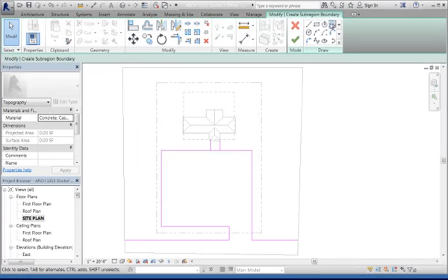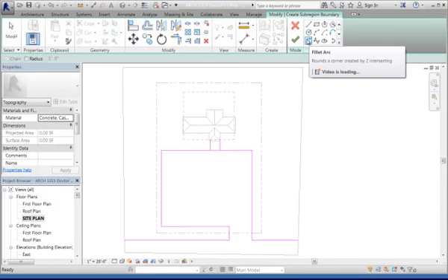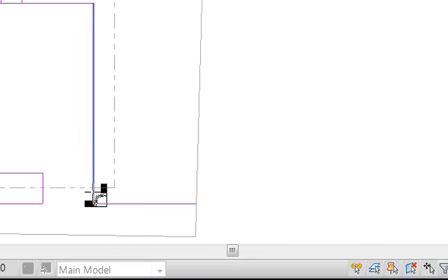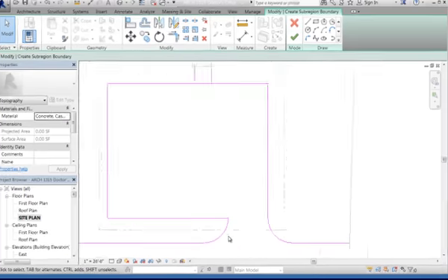This one, a fillet. And it says the radius is 15 feet. So I'm going to check that up here, go 15 feet. Then you hit your 2 lines that you want to be filleted right there. See? It made an extra line there I'm going to delete.